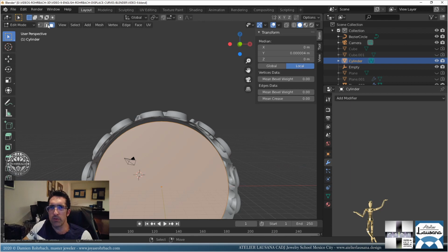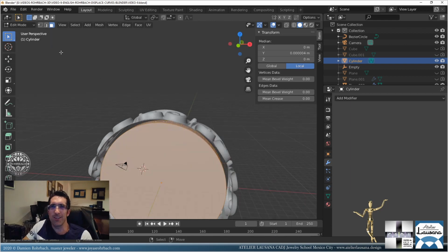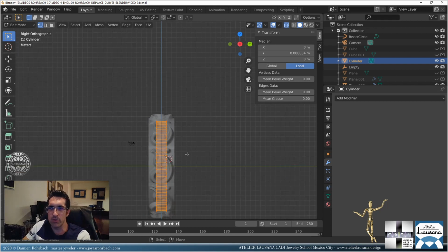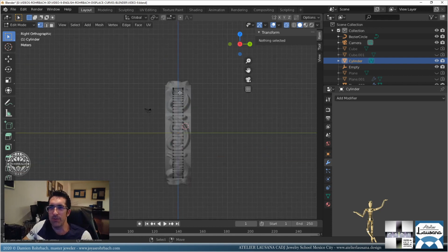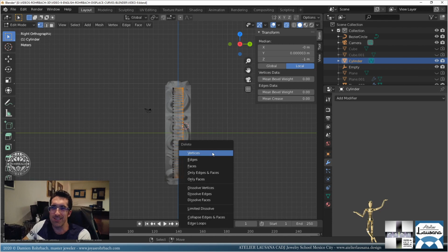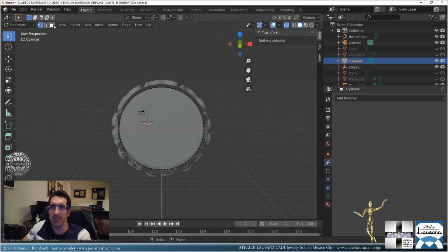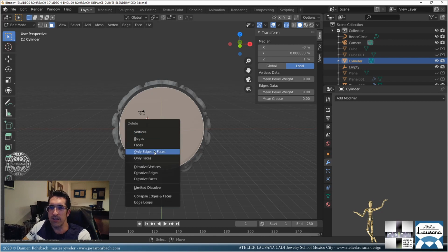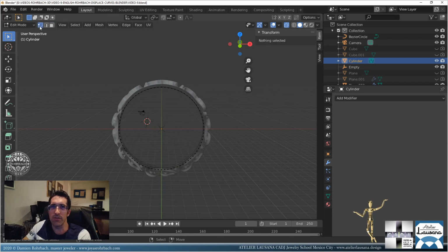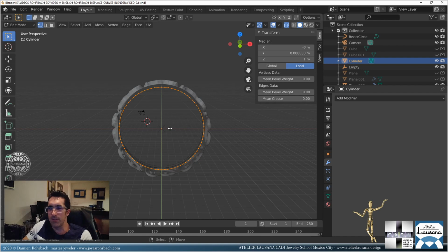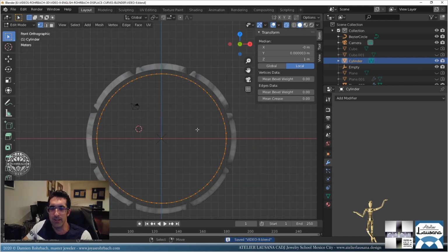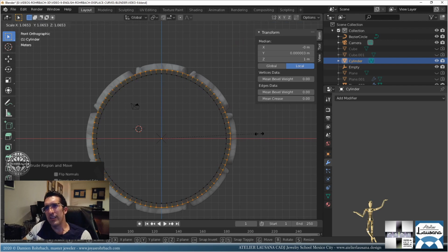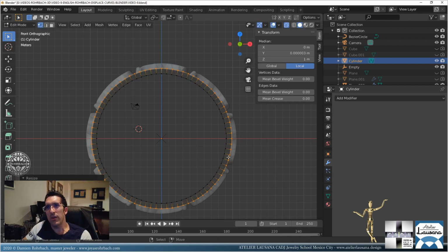So from that, actually, I'm just going to, well, funny me, I don't care. Let's go to vertex mode, Alt Z, transparency, Alt A, dissect everybody. I just wanted the circle, who cares? Let's even remove the front face. Delete only face. Okay, I have a circle, that's the same. I didn't want the cylinder at all. Now do extrusion, E, enter, S key, and come, let's say right there.